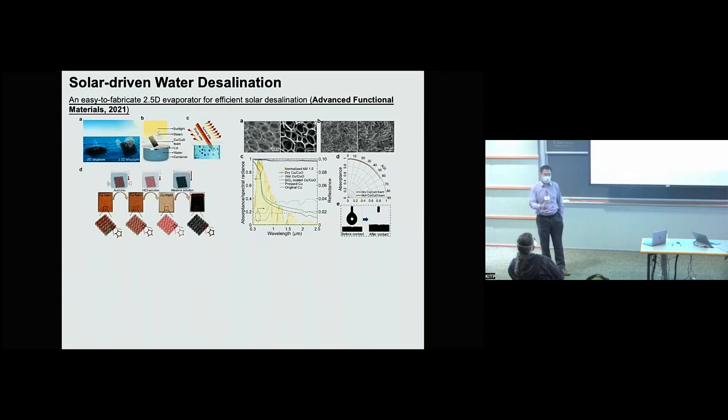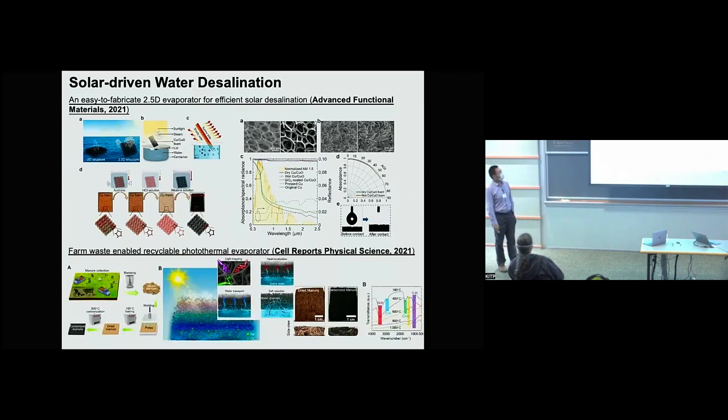They study hydrogel-based solar evaporators, and experimentally people demonstrated the water evaporation rate can go over the limit. The natural limit is 1.4 kilograms of water per meter square per hour. And our goal is to keep increasing this evaporation rate, the higher the better, with low-cost materials. But here I just want to give you a general idea about the interfacial evaporator.